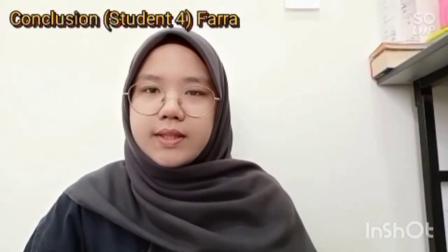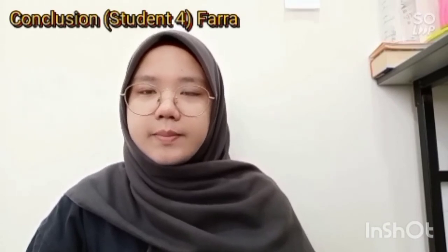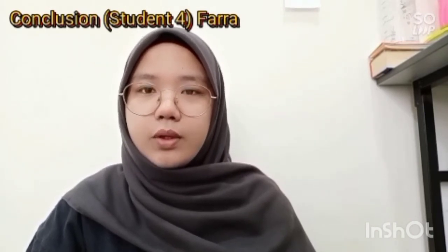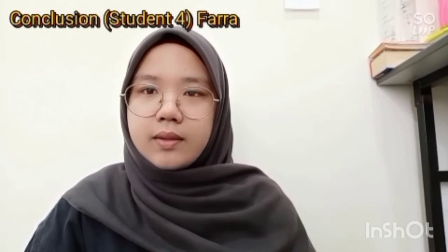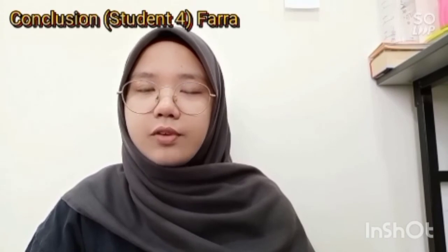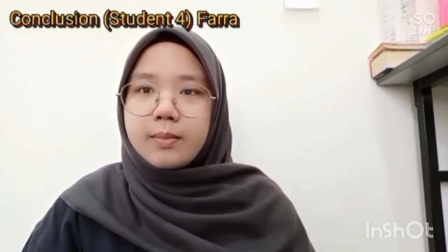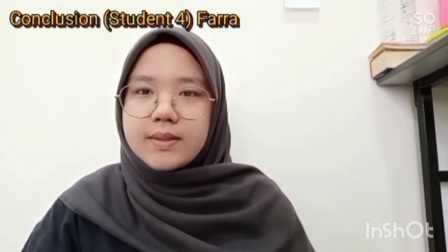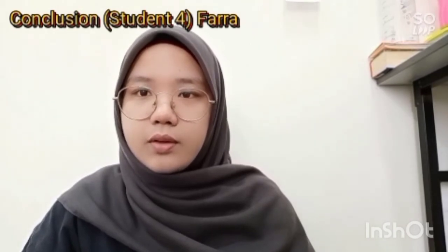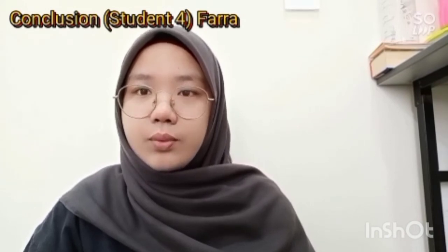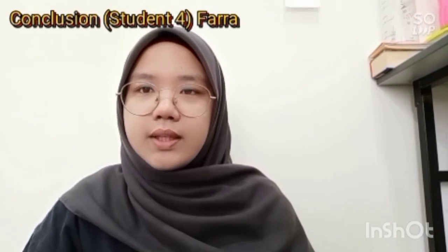My conclusion for this experiment is at the end of the experiment, it can be said that all the objectives were successfully achieved when moment of inertia, frictional moment, and moment of inertia using theoretical equation can be obtained based on the formula given. The flywheel is made to rotate by attaching a load to a string. From the results, the experimental value of moment of inertia is found to have a huge deviation ratio from the theoretical one. When the mass is increased, the moment of inertia also increases.